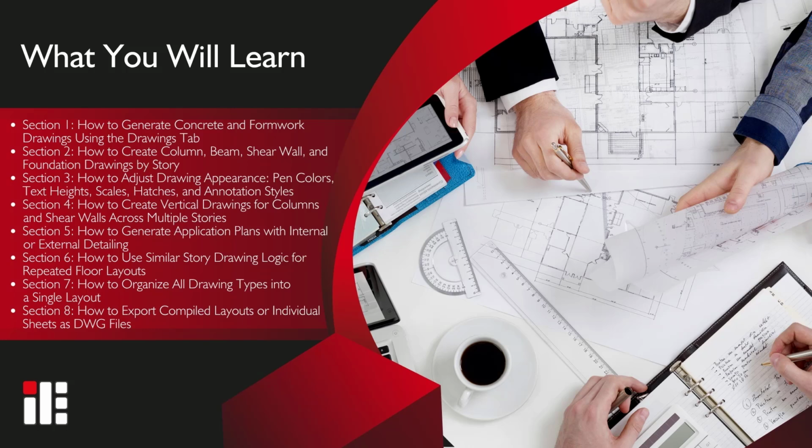You'll learn how to group drawings, clean up overlapping elements, and clone layouts for faster drafting. We'll also show how to use the Similar Story feature to automatically replicate beam drawings across matching floors. Once drawings are complete, you'll arrange them into a single layout sheet using layout blocks. Finally, we'll export that layout as a DWG file, ready for printing or project submission. By the end of this tutorial, you'll know how to produce clean, professional drawings and organize them efficiently using ideCAD.